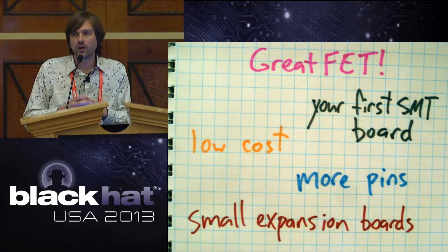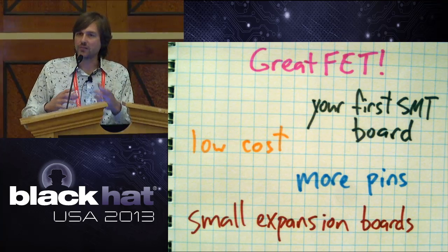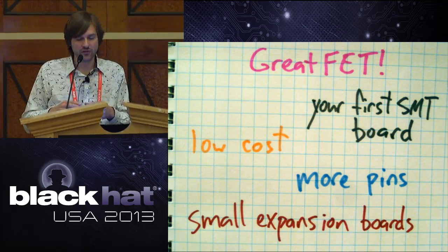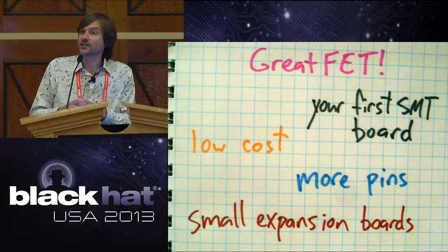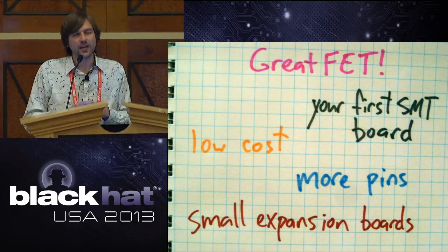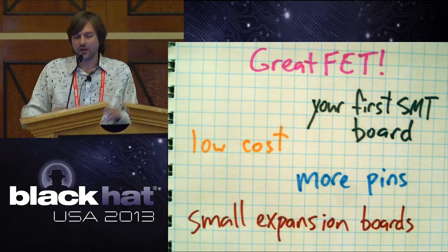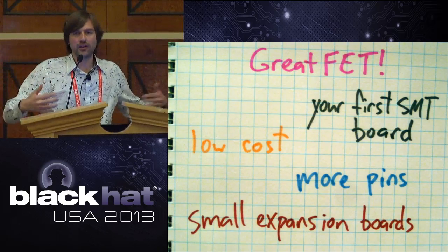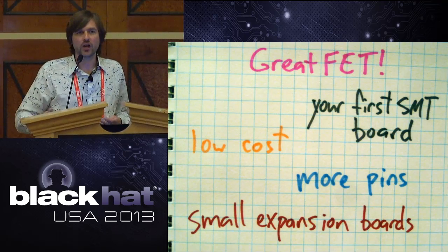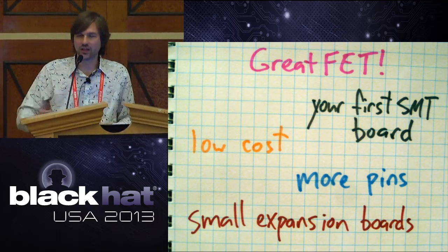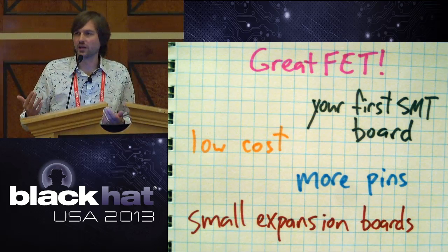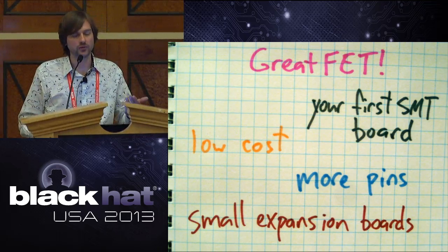It's a small board with not very many components, even though they're surface mount components. That may be something new for you if you've never soldered them before. It's something that's accessible for your first time SMT soldering project, and you don't have to have another board to bootstrap the process of loading code onto it. You can just solder it up, plug it into USB, and it automatically starts up with a USB bootloader for you to write code for it.